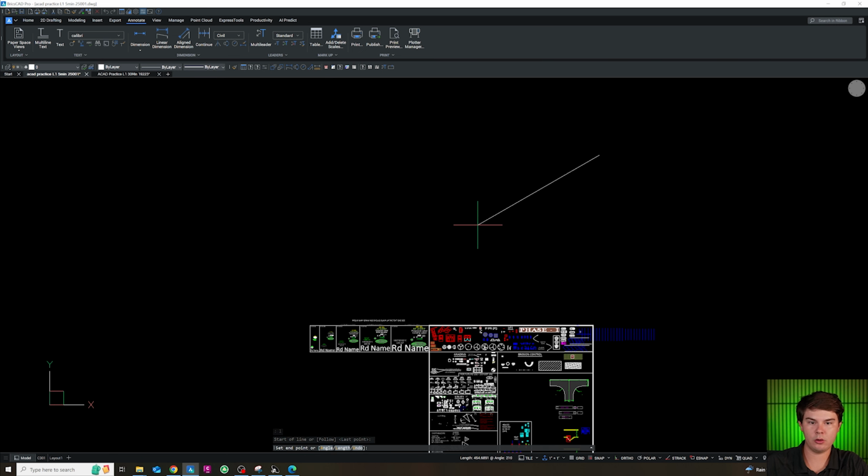To do this, use L for line, and then to type in, you have to type in the metes and bounds. So I'll use @ and the distance, which is 219.0 feet, and then use the less than sign, and I'll use south 55 D for degrees, 03 minutes, 32 seconds west. And now I'll be doing @157 feet, less than, south 34 D for degrees, 56 minutes and 28 seconds east.